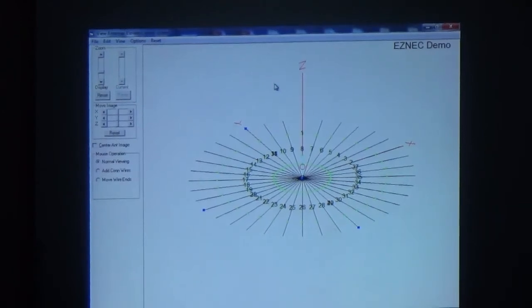They are above the ground. That is a restriction on the NEC2 engine. They cannot be touching the ground. Do I have to set the elevation? Yes, it will take care of that. Now, you should go in and specify it at a certain height, but he mentions in the user manual that, in order to model buried radials, just putting them above the ground is close enough.